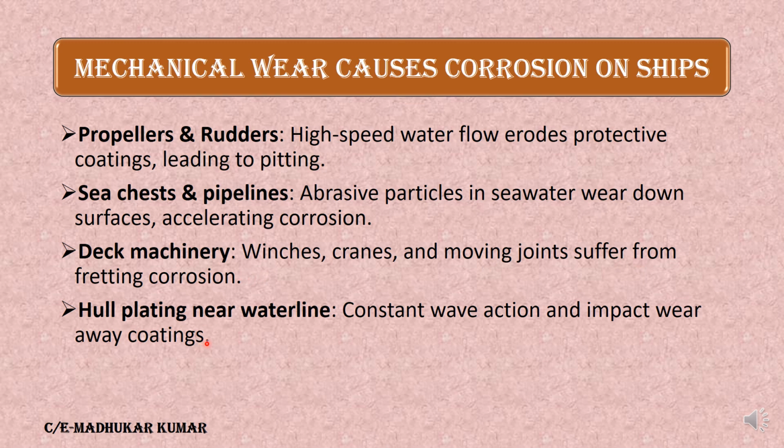And hull plating near the waterline. Near the waterline, you have oxygen availability also, electrolyte availability also, and the constant wave action and impact wear away the coating.